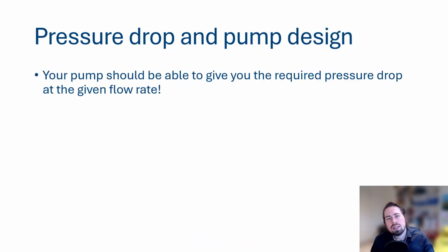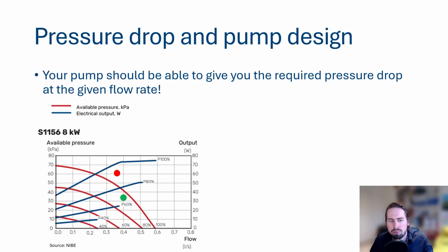And that's why pump design is so important. Now for smaller projects, this pump is included in the heat pump itself. So you typically do not design a primary pump, but it's important to check whether or not your pump can actually handle the larger pressure drop.